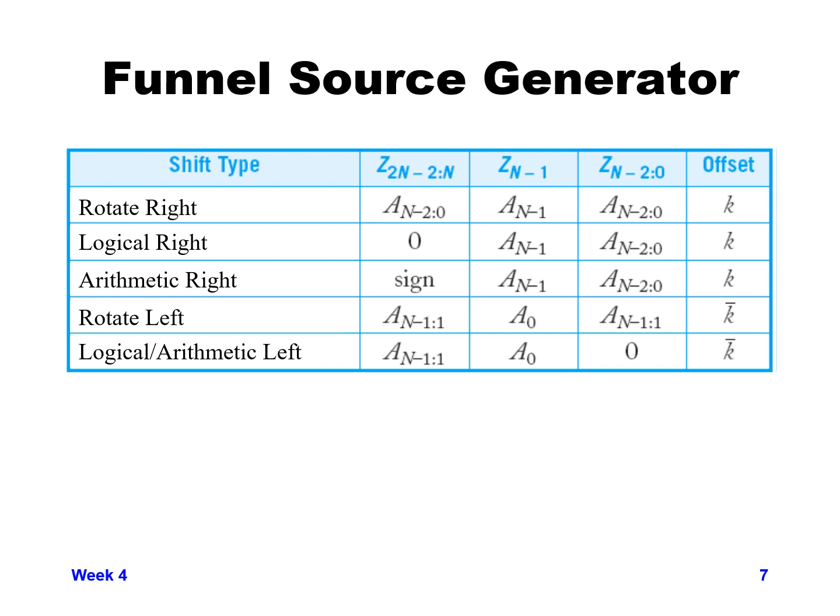So I mentioned on the previous foil that we had this funnel shifter, where we had to fill a data value of z with a larger number of bits than our original y data value. This chart here is meant to show what we fill in the left hand. So we have the y value in there, then we have some extra bits on the left hand side of y and some extra bits on the right hand side, and the question is, what do we fill that with?